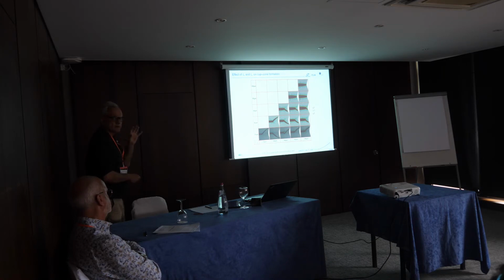We see that when we increase the length associated with void growth, the length of the central part, which is flat, tends to increase. This is also very clear on this line. And in some cases, you see that we only have flat fracture. It really depends on the ratio of both lengths.